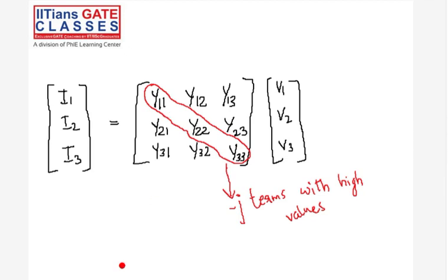Okay, cool. So that's why we say that since it is a summation of all the components, usually we get the diagonal elements as very high value minus j terms. So this is something to remember when you're looking at the Y-bus matrix. When you're analyzing problems, it will make sense to you very quickly. And this would be positive because it is the negative of that element. So this would be something like j2 or j10.